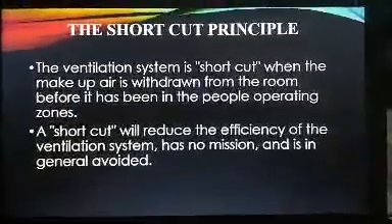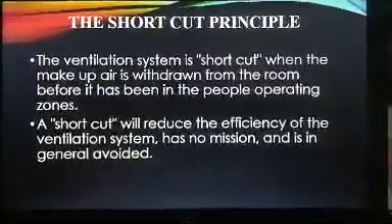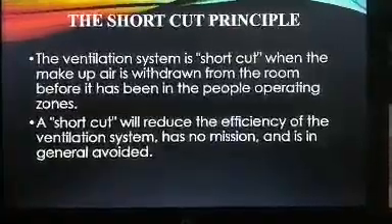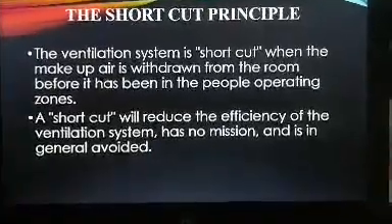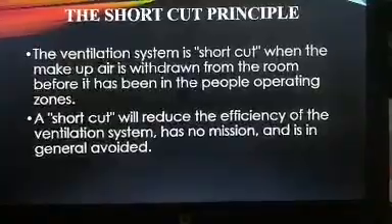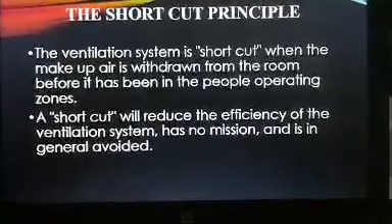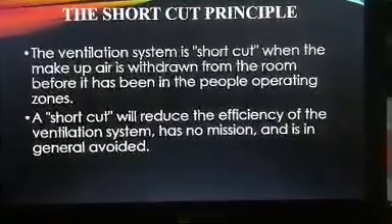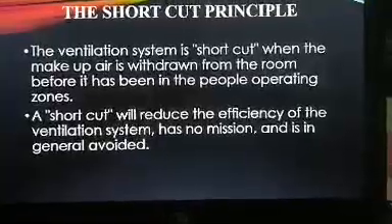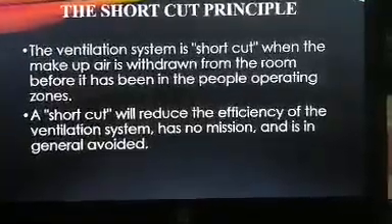The shortcut principle. The ventilation system is shortcut when the make-up air is withdrawn from the room before it has been in the people operating zone. A shortcut will reduce the efficiency of the ventilation system, has no mission, and is in general avoided.